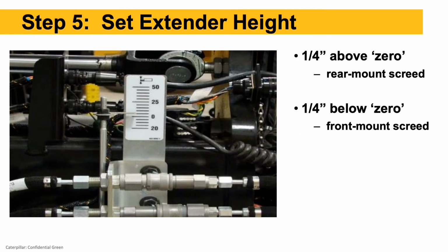Step 5, we'll set our extender height here. And again, this is really important because what this is actually doing is setting our angle of attack that we talked about. So that 1/4 inch angle of attack that I talked about earlier, this is where we're establishing that.